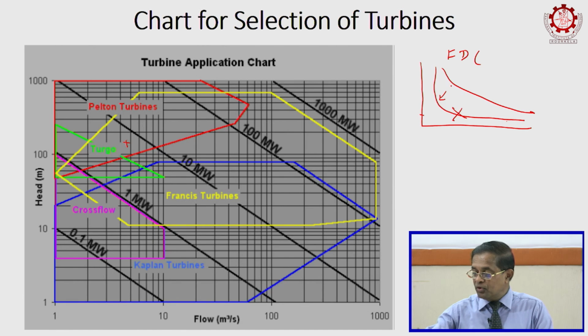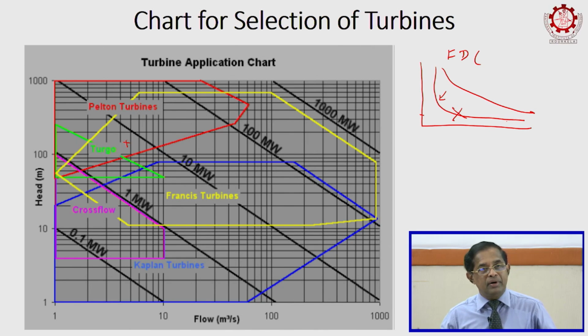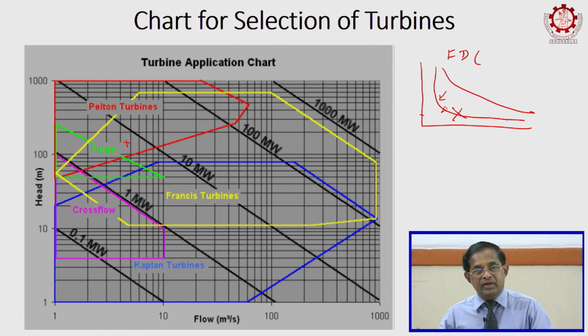This is a good one because water is retained in the forest or whatever the vegetation cover, and slowly released over the years, then you can utilize it more, right. So, you can tell the properties of the catchment area by looking at the flow duration curve without even visiting the site. Most of the surfaces are rocky and less water retention, right. So, these are important things when you are looking at the project.